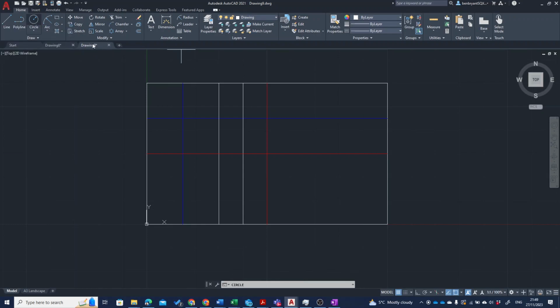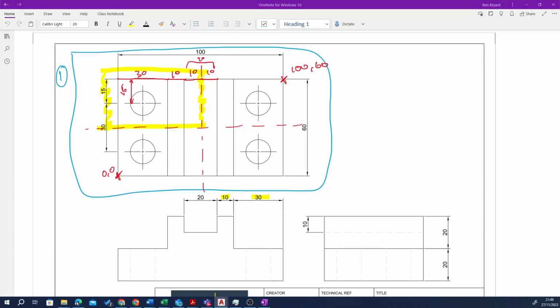Next one, circle. Click on the center point of those 2 objects, the intersection point in my drawing layer, and these are going to be 15 mil radius. Okay, so that will spin out on that one because when you click in 15, it will fill the whole shape. So it's actually diameter of 15.